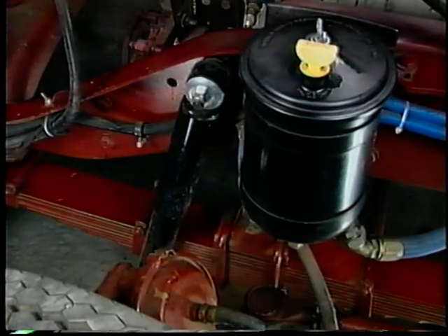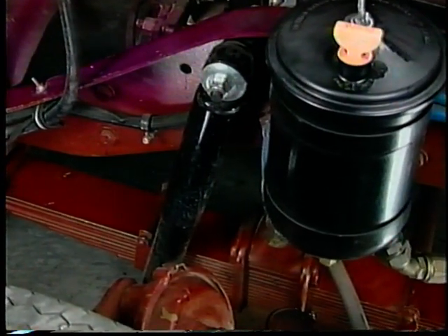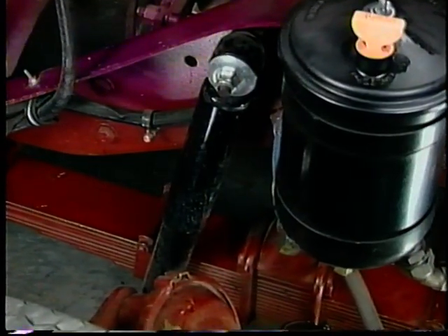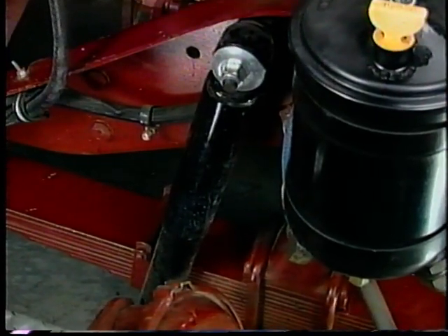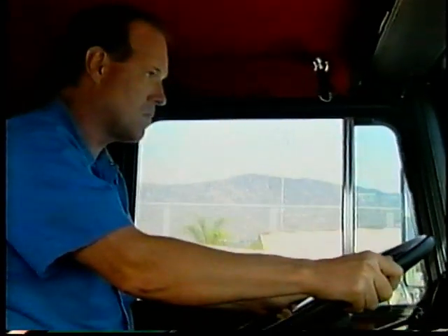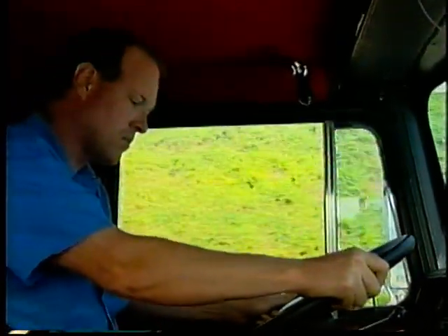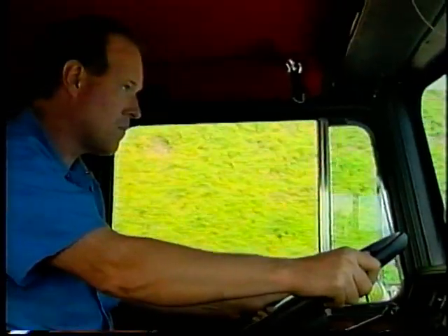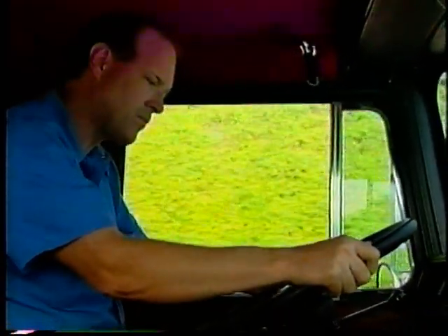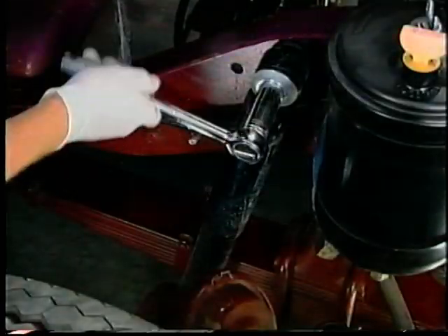Along with providing the pivot points for turning, the front suspension must also keep the wheels on the road to ensure safe operation during steering, riding, and braking. This is the main function of the shock absorbers. Worn shock absorbers will result in excessive jouncing and rebound over bumps that can cause the front end to bounce and the steering wheel to oscillate, and often a loss of directional stability as the spring oscillations are uncontrolled.